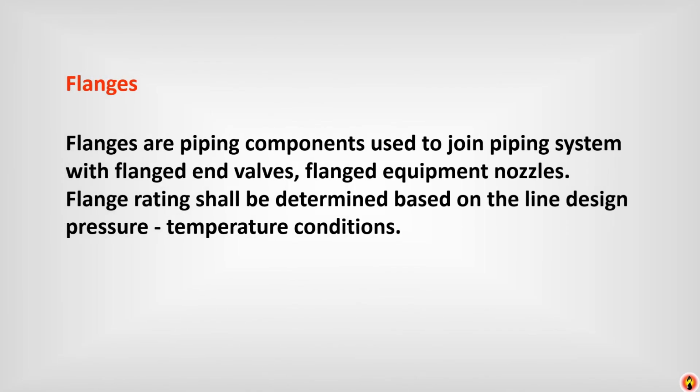Flanges. Flanges are piping components used to join piping system with flanged end valves and flanged equipment nozzles. Flange rating shall be determined based on the line design pressure and temperature conditions.